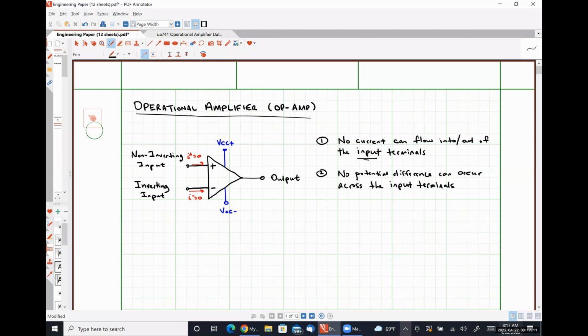Well, for an op-amp, the open loop gain is usually somewhere on the order of a few hundred thousand volts per volt to a few million volts per volt. And the end user doesn't really get any choice in that. It's set by the manufacturing process, and then it's just going to fall within some range due to small variations in the manufacturing process.